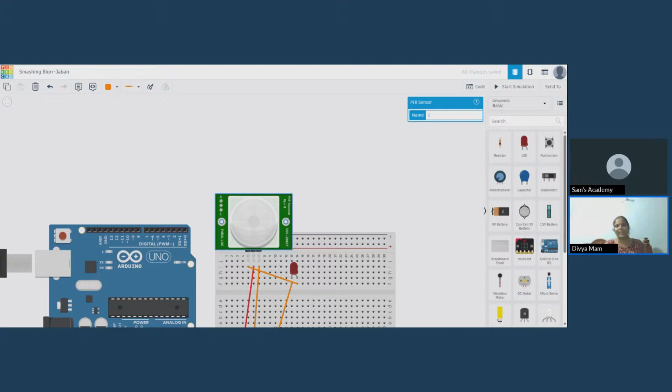Okay, digital read and write. So here, are we going to use digital read or analog read? We have a confusion. How could you choose digital or analog here? The sensor is going to sense the presence and absence of an object, am I right? Then why do we need to go with analog here? The value will not vary in between, right? Whether it will be high or low. So we can go with digital, 0 or 1, high or low. So digital read or digital write we are going to use here.